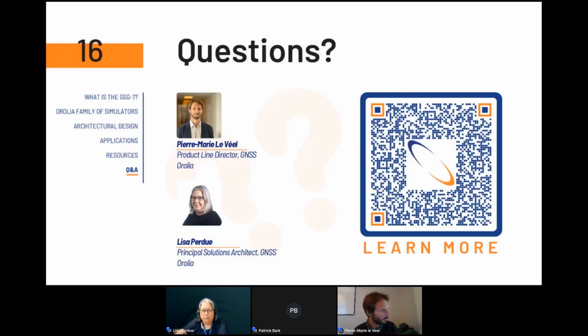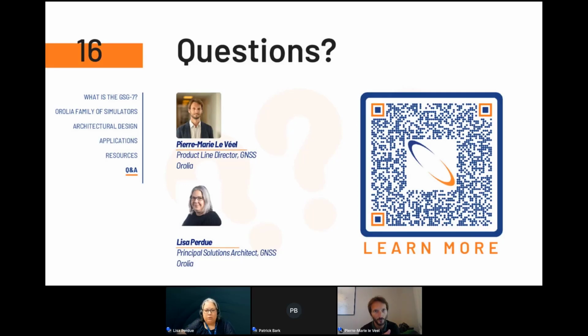I can take this one if you want. So first about the signal simulation, yes, we do support all the Galileo signals. So we support E1, E5A, E5B, and E5 AltBOC even, and E6. And we also support the HAS correction from Galileo E6. And about the LEO simulation, I guess the question is about the receiver embedded on a LEO satellite. So yes, we do support that. As explained during the presentation, we can simulate any kind of trajectories. So we can simulate trajectories on a LEO satellite with the dynamics on a LEO satellite. So yes, we can simulate these trajectories and these signals on the GSG-7 simulator.